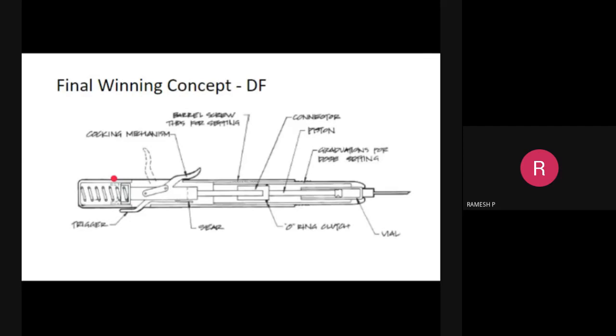And here we are supposed to focus on a few things, being in a product development team. We should not simply select the concept which has the highest rating and the first rank. Always we must do, as I said, a sensitivity study. Look for uncertainties. Using our FMEA, look for potential failures. Discuss the relative weightage and relative rating of each and every aspect over the winning concept. The PD team must always check whether any uncertainty about a particular value will have a maximum impact on the final winning concept.